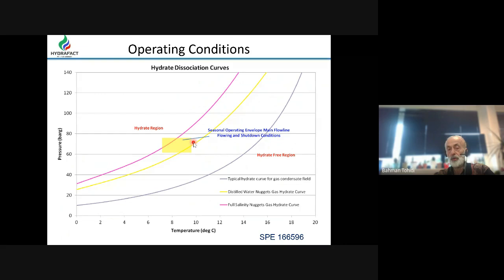They noticed that up to 20% it won't block. And they put the limit of salt to 5%. And from the increase in salt concentration from 4.5 to 5%, they realized that they were injecting too much inhibitor.